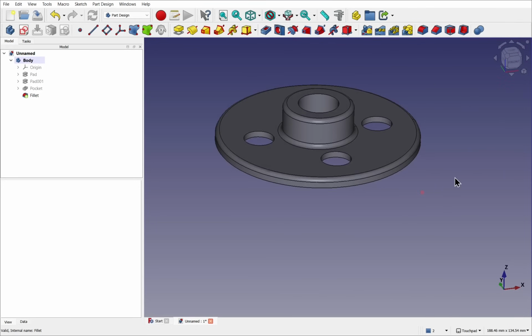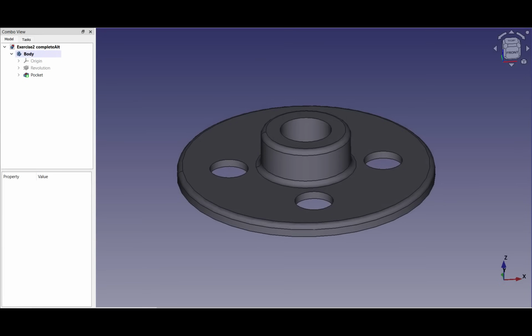Higher deviation means you have less CPU cycles to deal with the model. Lowering that deviation cleans up the model, cleans up the view, but it requires more compute time to do any modifications. Earlier I mentioned that this model can be created in a number of ways. We can reduce the operations via a different approach, a revolve. As you can see, we have reduced the operations by half. We will talk about how we identify the models that would use this workflow in the next video.